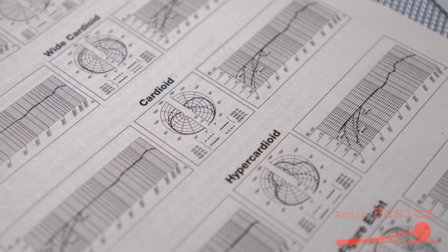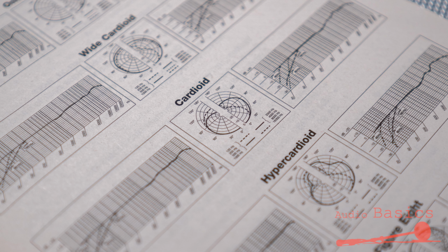Okay, before we dial in the proper preamp setting, I want to address how to speak into a typical vocal microphone. First, determine if your mic is either top address or side address. This is extremely important to how your mic sounds. The paperwork included with your mic should show you what direction it's designed to pick up from, or you can just look it up on the Google. You want to make sure that the diaphragm of the mic is pointed directly at your mouth or as close to that angle as possible. Sound, as we interpret it, is changes in pressure, and when we speak, its primary source is your mouth. As such, we want to make sure that our microphone is properly angled to catch the most sound possible from its source.